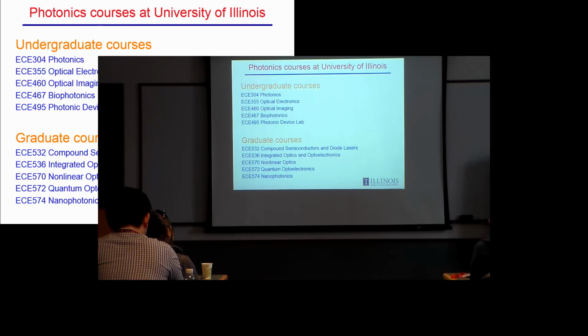Single-mode fiber is more expensive because you've got very exacting control of that size. From an engineering perspective, the dispersion relationship for multimode fiber is very complicated. Lots of different modes can go in it, and it turns out they all transmit down the fiber with different refractive indices. Slightly different, but different nevertheless.